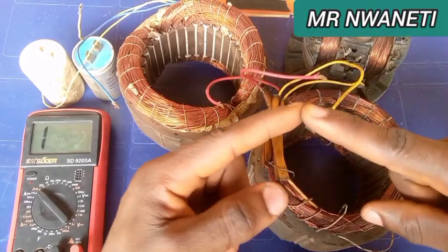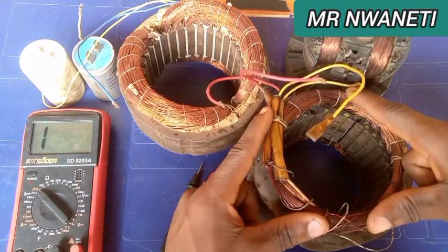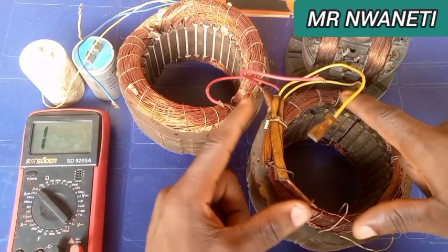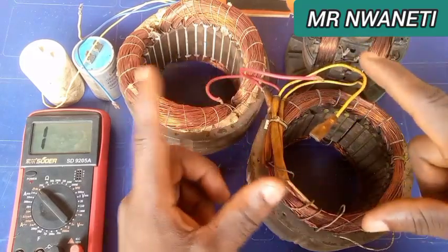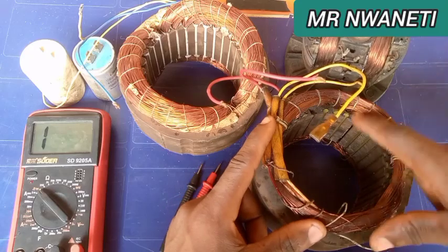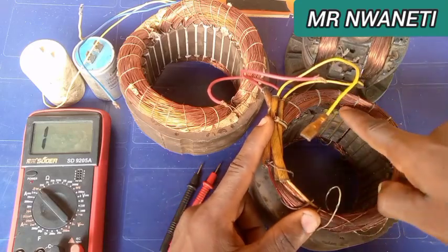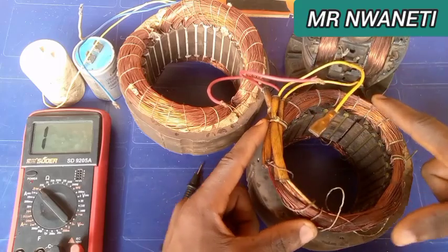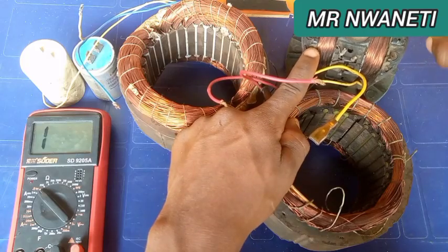Assuming you have 2500 rpm, maybe 3000 rpm, and you want more voltage depending on the project you want to run, this is the basic way: either by increasing the turns from the exciter, or increasing the coil from the mains, or putting more turns on the rotor.